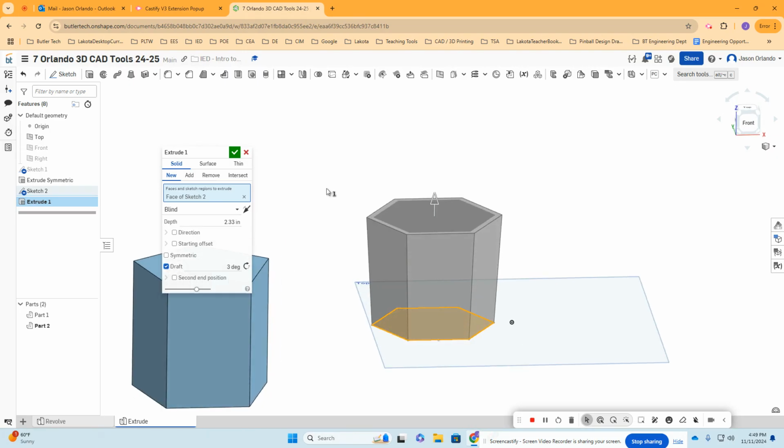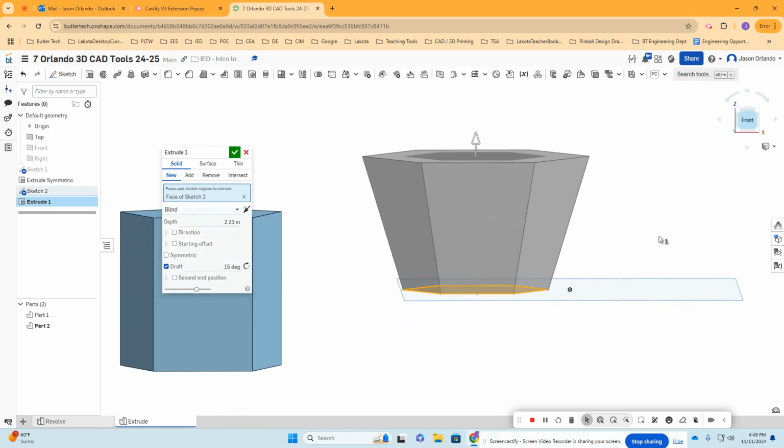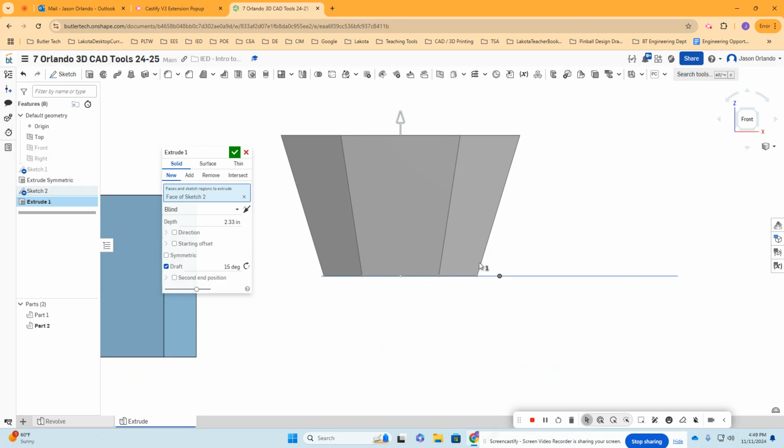see if they could figure out what happens. What you should see happens is that it actually kind of tapers out or in, kind of flares out, whichever word you want to think. Now the angle that you're specifying is really, think of this point here, had it gone straight ahead, straight up, where it would have ended, think of a vertical line that would be right here. This flare out is really that angle here.